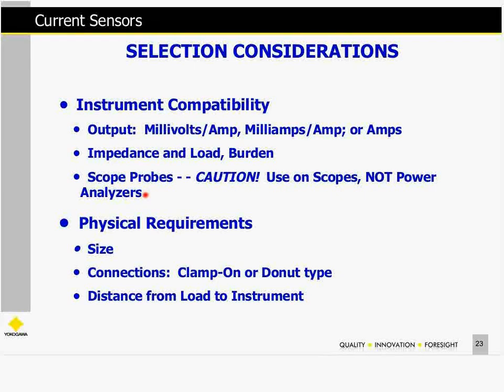The power analyzer has a different type of input circuit than a scope typically does, and a lot of times we will see problems because they are not matched with the electrical input characteristics of the amplifiers of the two different types of instruments. Then, of course, your physical size, how much room do you have to put your CT in the circuit. Clamp irons, they're very handy.